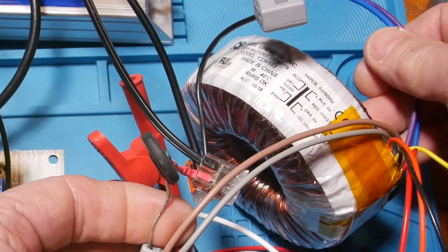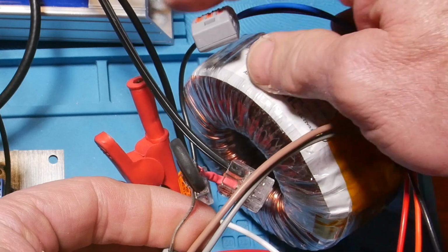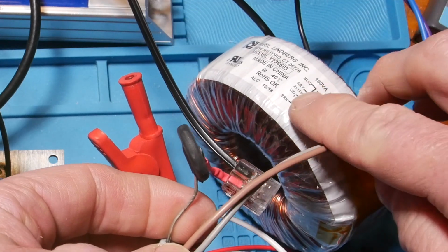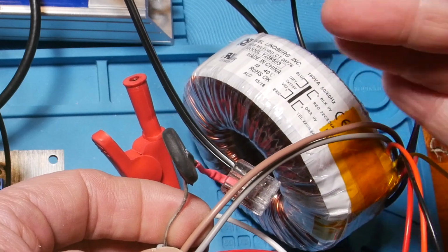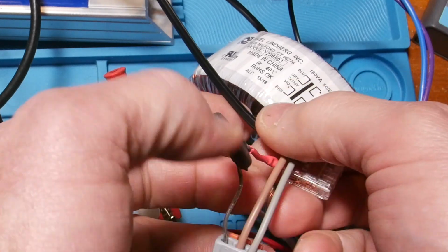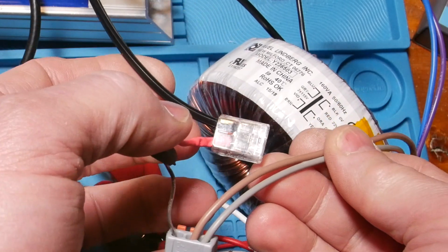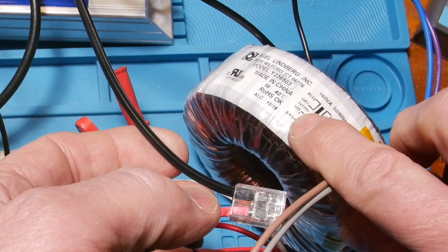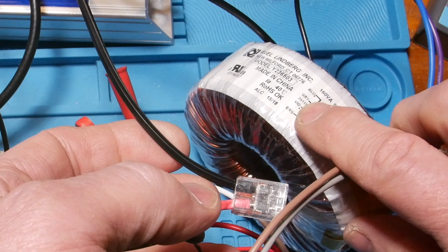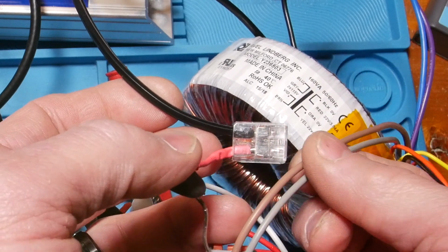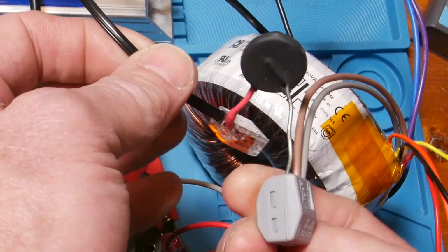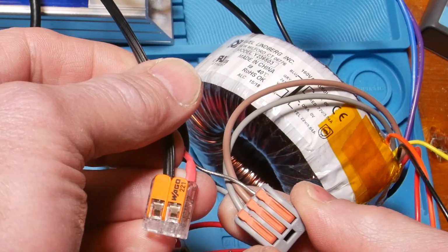And I know I do this backwards from some people, but as long as you're consistent, you either call the dot your negatives or your positives, and you treat them the same on both sides, okay? So I'm putting my bottom of these two windings, I'm in the US, so I put them in parallel. If you're at 220, you'd put those in series. But so I'm using these really cool little connectors to put them together.